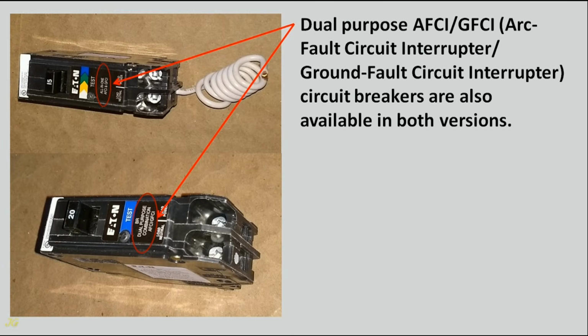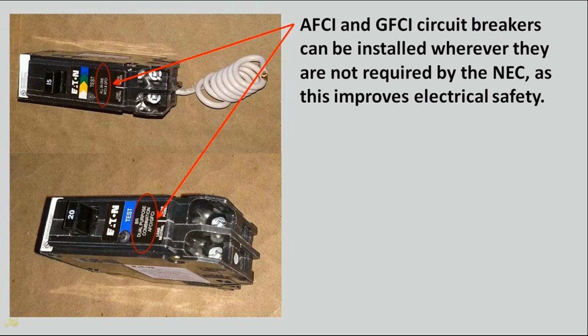Dual-purpose AFCI, GFCI, arc fault circuit interrupter, ground fault circuit interrupter, circuit breakers are also available in both versions. AFCI and GFCI circuit breakers can be installed wherever they are not required by the NEC, as this improves electrical safety.